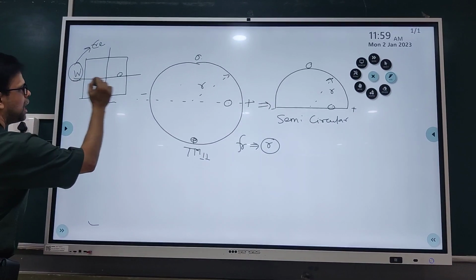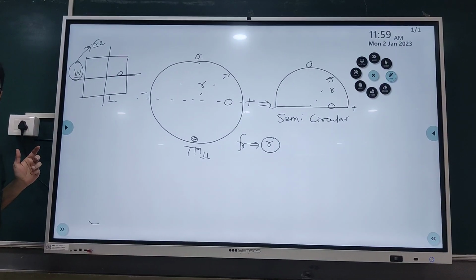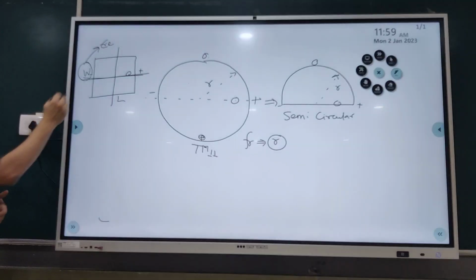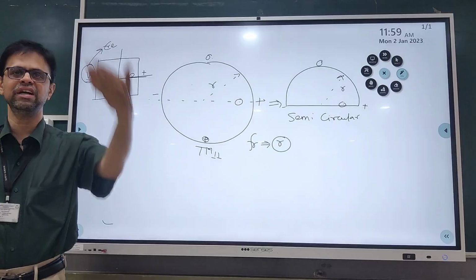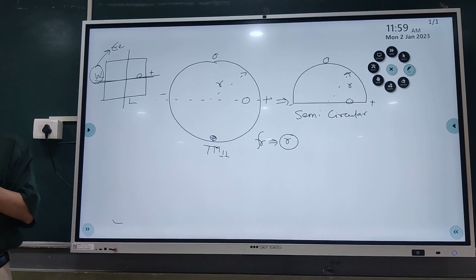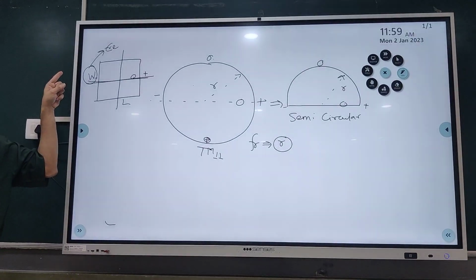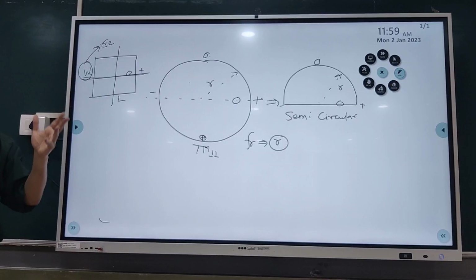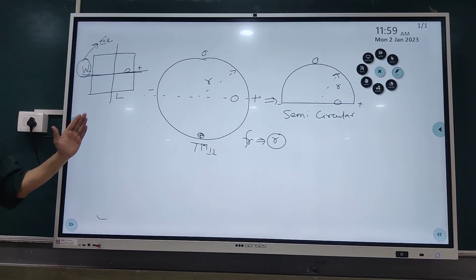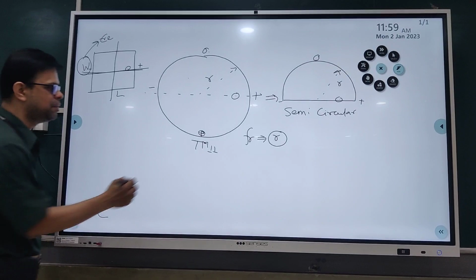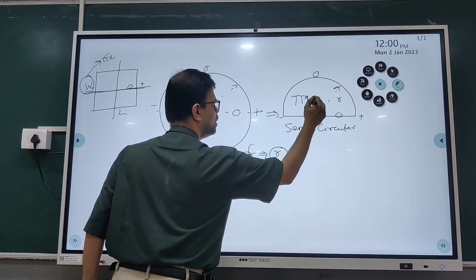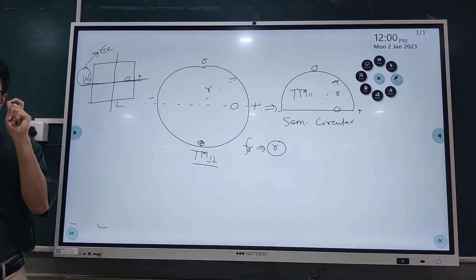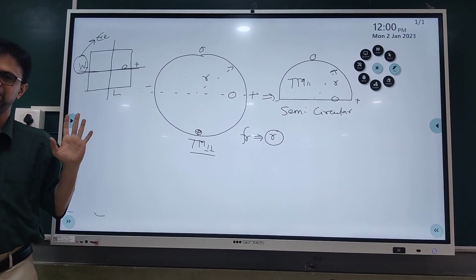Unlike in this case, if I use a half, because the same principle can be applied over here also. So if I use the half of the geometry with respect to the fundamental mode, here the width is getting affected. That will affect your effective dielectric constant, and because of that, your resonance frequency will change. Same concept, same equivalence can be dealt with over here, because ultimately the width of the patch is also reduced. The area of the patch is reduced. But the effect of variation in the frequency of this fundamental mode TM11 in circular and semicircular is lesser. You will see a drastic variation in the frequency here, because L and W both decide your resonance frequency.